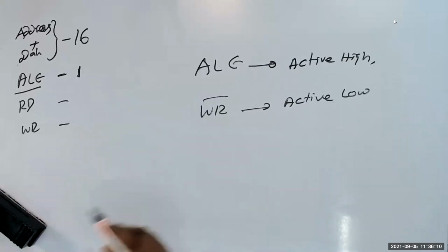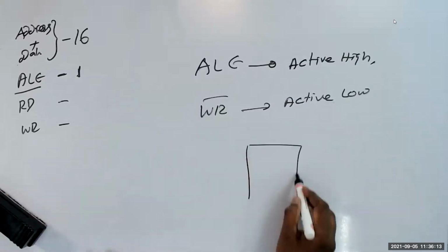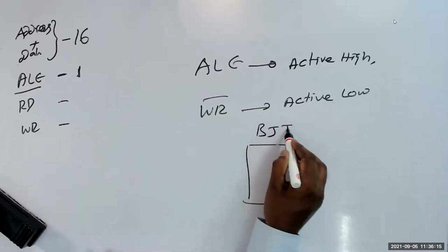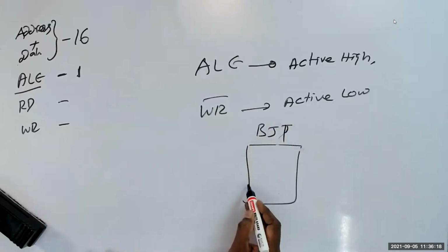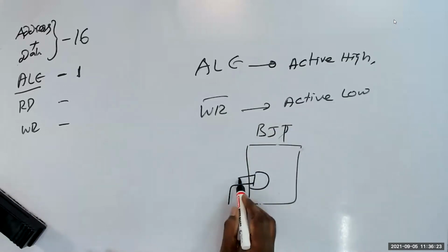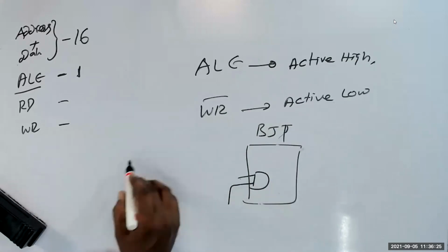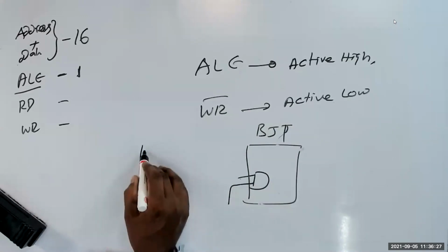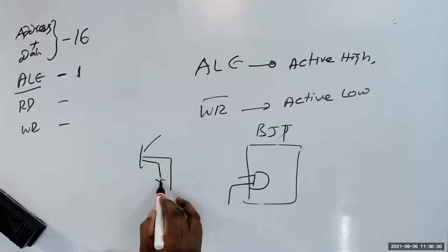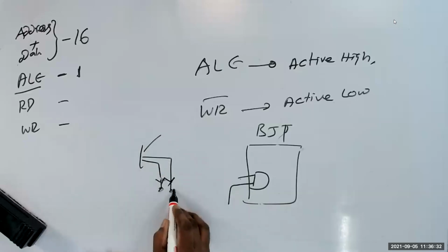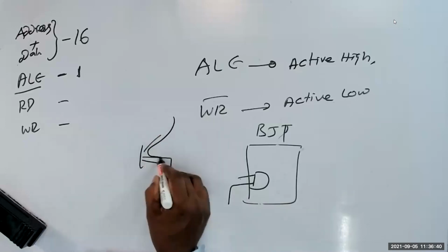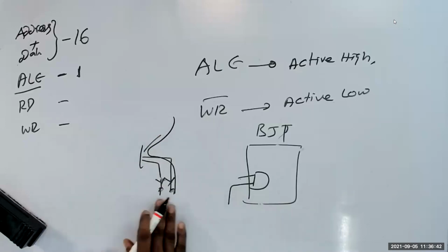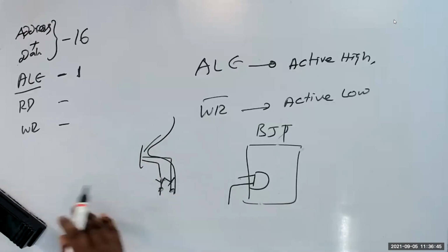The reason was those days they were using BJTs most. In a BJT, the input pins of an AND gate or whatever IC have a transistor. They have multiple gates, multiple pins. They leave it like this. The moment you connect it to ground, it will consume current, it will conduct. The moment you leave it open, it will not consume current. So they leave the pins.